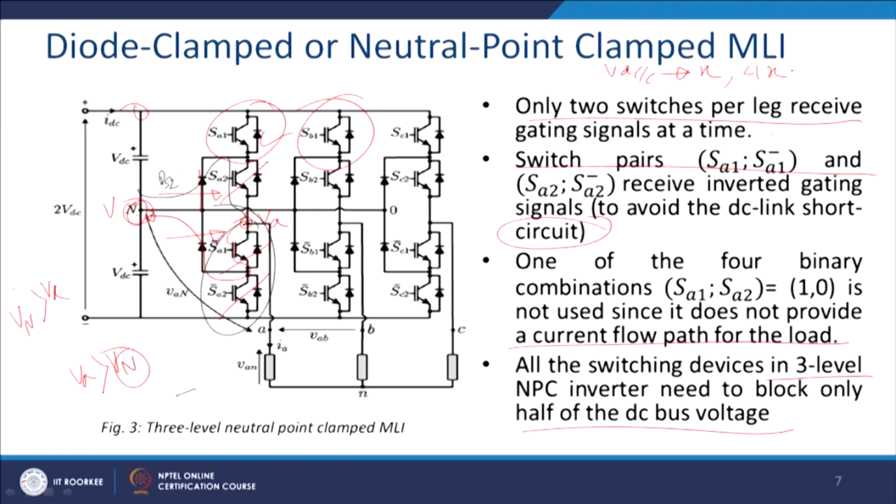But if the IGBT price at VDC is 2x, then you require 2 IGBTs, and it is again 4x. So cost wise we do not have much problem, but in terms of benefit, you get lower THD, lower value of filters, greater longevity of your devices, and all those advantages.